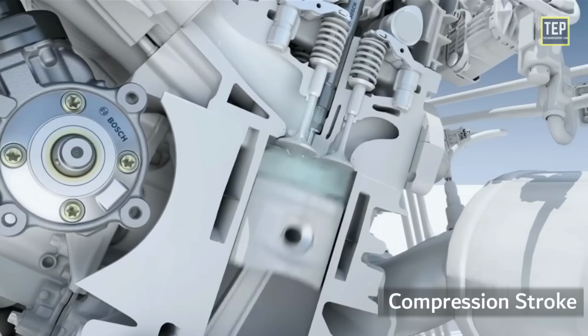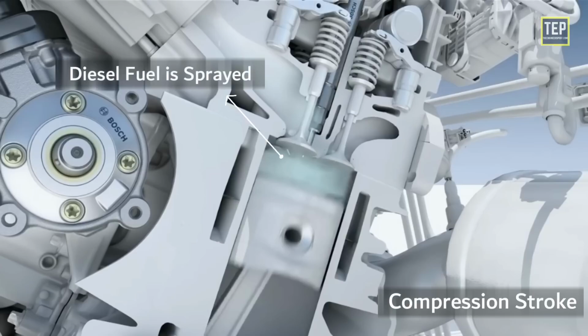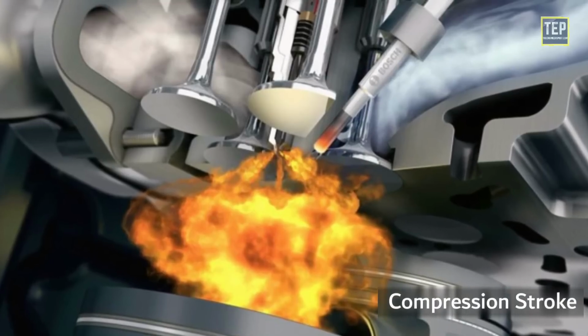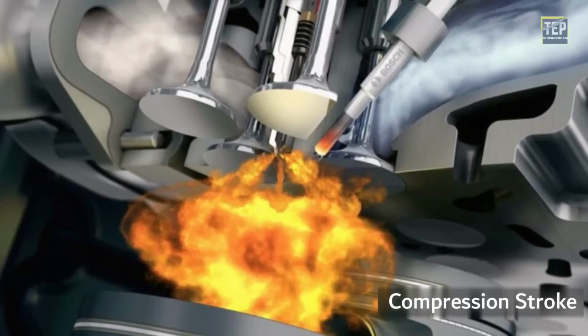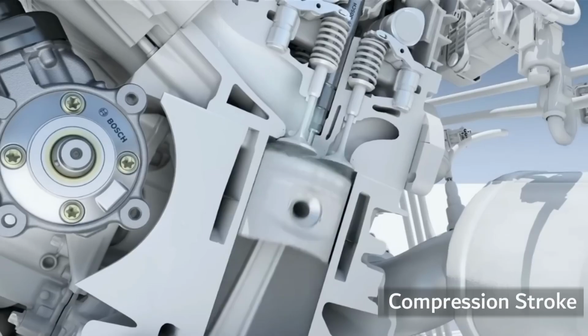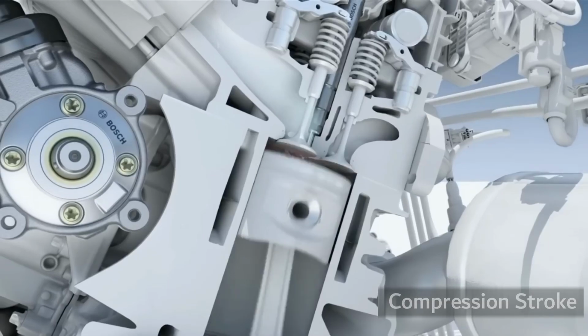Just before the piston reaches top dead center, diesel fuel is sprayed inside the cylinder. The fuel is sprayed by means of a fuel injector at a very high pressure, overcoming the pressure of the compressed air. The fuel gets mixed up with air, which contains oxygen. Since the fuel is a hydrocarbon, the temperature of compressed air is sufficient to initiate the combustion, and the fuel is burnt.